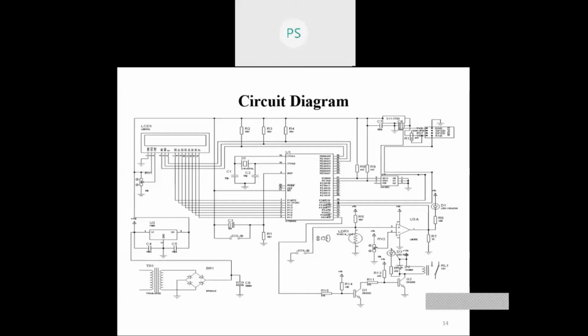To get the pulse from the energy meter, an LDR is used as an optical sensor. The resistance of the LDR changes depending on the light falling on it. In the circuit, the LDR is placed as a part of a voltage divider circuit. According to the voltage divider rule, when a 10K resistor is used as R1 and the LDR is used as R2, with Vin as plus 5 volt, if light falls on the LDR, the Vout will drop.